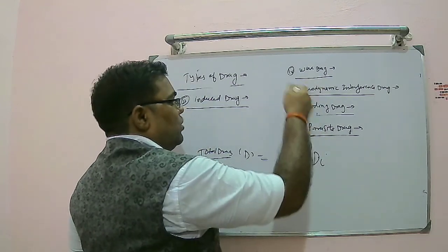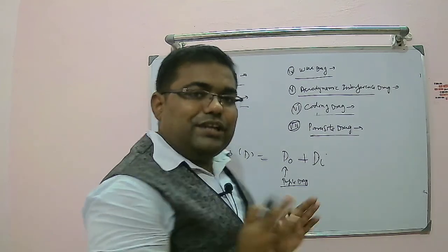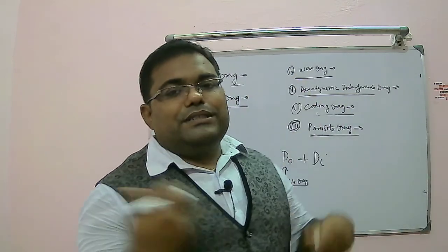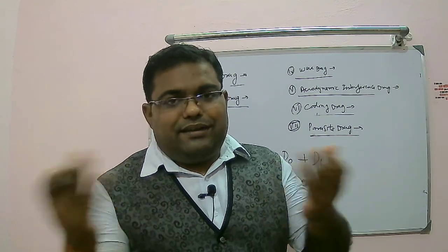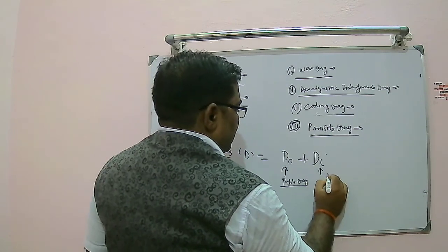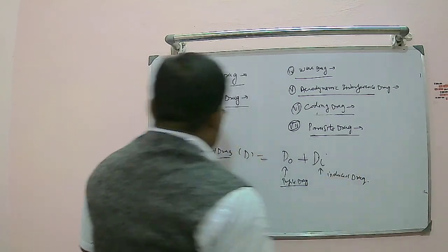This is due to geometry, right? All these drags depend on the geometry of the object which is traveling in that environment. Interference also depends on the geometry. Shock wave formation also depends on geometry. So the drag due to geometrical features is profile drag, and the second is induced drag. Induced drag is this.